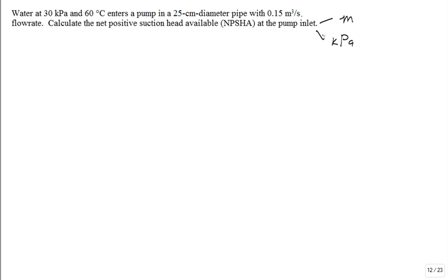All depends. We could calculate it both ways easily. Once you calculate meters, say, oh, I need it in kilopascal, let me give it to you right now. It's easy, okay? So which way do you want to do? Meters. So it'll be the inlet static pressure divided by rho g of the fluid. It'll be the V squared over 2g, so I'm going to have to get the speed of the fluid. Often the speed of the fluid's negligible in the contribution to the total head, but we're doing it this way.